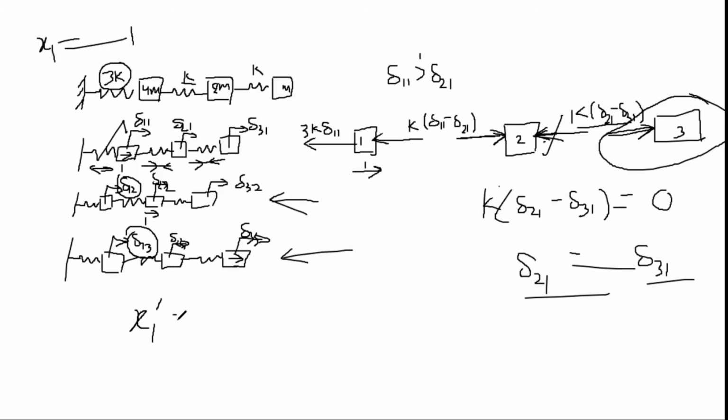But you have to calculate the new deflection after applying the initial forces. So this would be the summation of deflection at different loads, and at point 1, delta 1,3. And these deflections are because of the unit load applied at different masses. So if I apply force F1 here, then this would be F1 delta 1,1. And if I apply the initial force at point 2 as F2, and the inertial force at point 3 as F3, then the new deflection at point 1 dash would be given by this formula. Hope you have understood this.